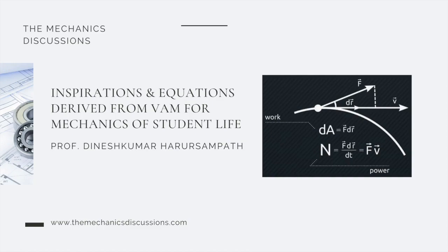Excellent question. The Navier-Stokes equation has been established as the pinnacle of fluid mechanics over a long period of time. Now, this is basically a differential equation, a differential approach, like what we are doing with Newtonian mechanics, for example, but it is using an Eulerian field instead of a Lagrangian field.